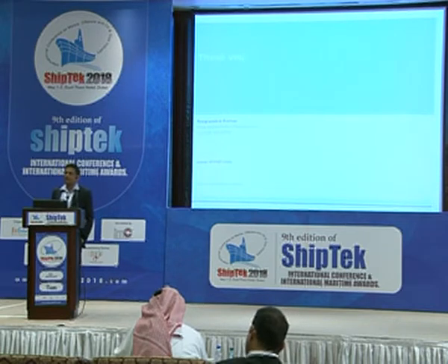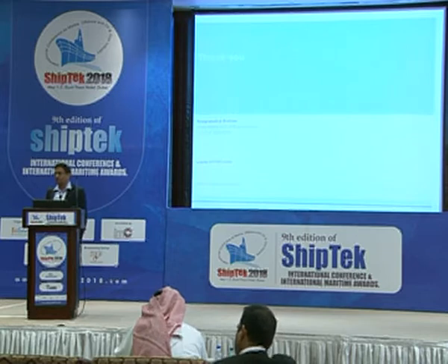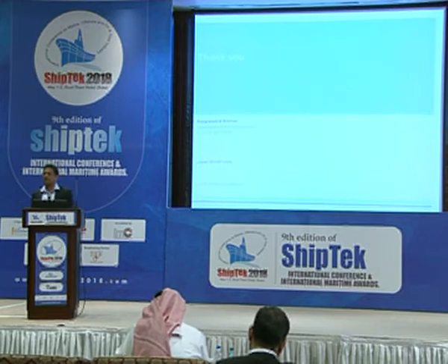And this RBI is based on some calculations also. If you can prove that a particular joint will not crack for another 10-15 years, and the previous inspection report is good, and all the coating conditions and the cathodes and all are maintained, then yes, we have taken the decision. But not very frequently, yes, but a few cases are there.